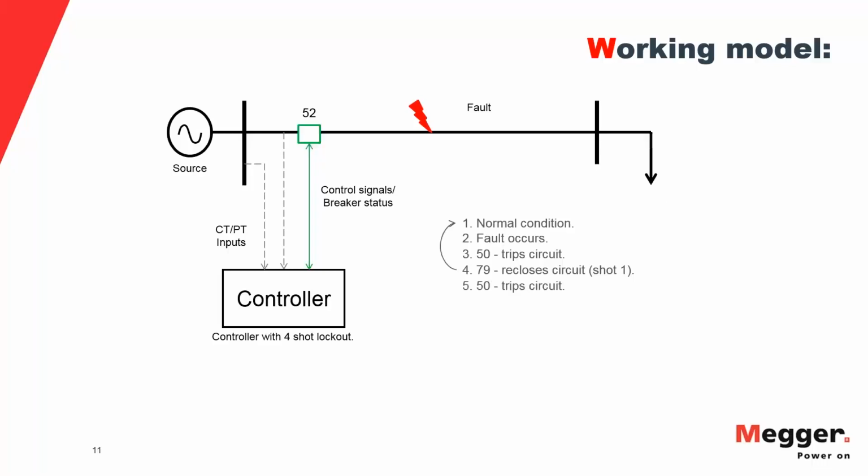So it opens, does the same thing again, waits, because maybe the time that it gave the first time it was open wasn't enough for the fault to clear, and it closes again. And it repeats that cycle for a maximum of around 4 times until it determines whether the fault is there to stay or if the fault cleared itself.